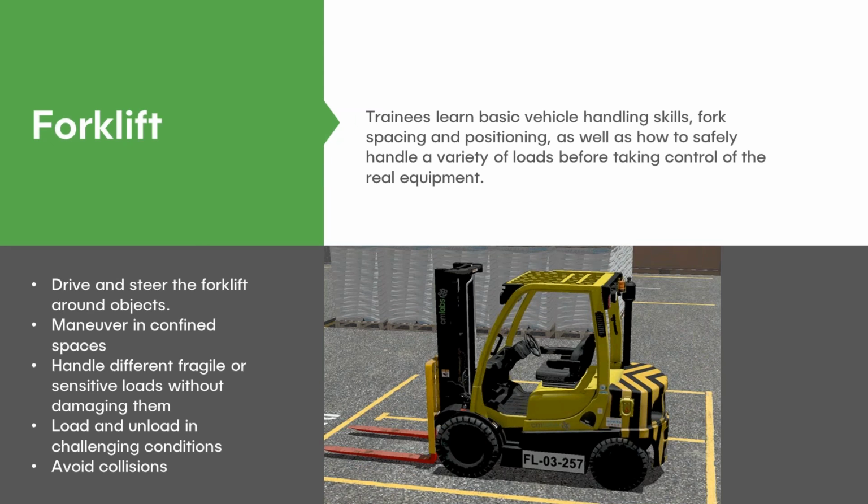The forklift. This one was designed for the port, but we use it inside the construction. It's a smaller one, for maneuvering around small spaces. It's got the ability to change the spacing between the forks. The heads up on that one for people who have never driven a forklift is the rear wheel steering. It isn't intuitive, and lining up the forks into the pallet is a challenge.